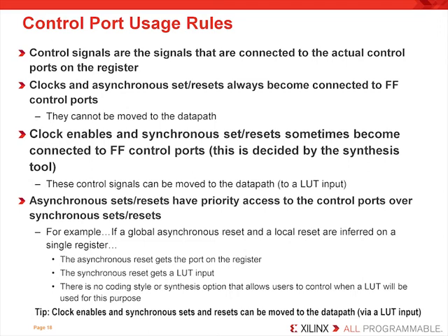Clock enables and synchronous sets and resets sometimes become connected to a flip-flop's control ports, and this is decided by the synthesis tool unless you place the appropriate synthesis tool attribute to dictate how that's going to get mapped to the register's control ports. These control signals can be moved to the data path, and as we've seen from a couple examples, this gives the implementation tools a great deal of flexibility. So we do recommend the use of synchronous sets and resets and clock enables.